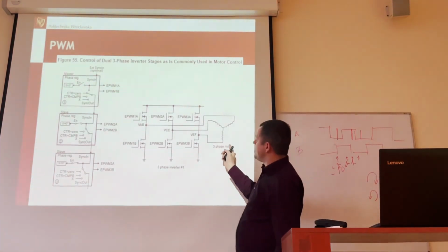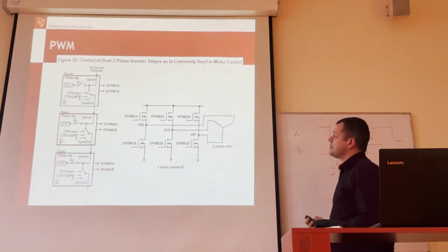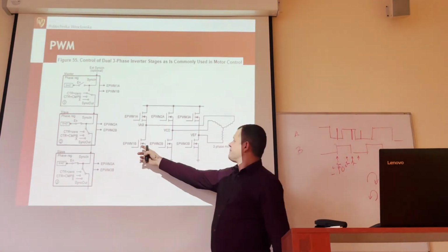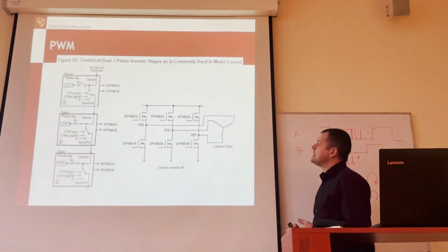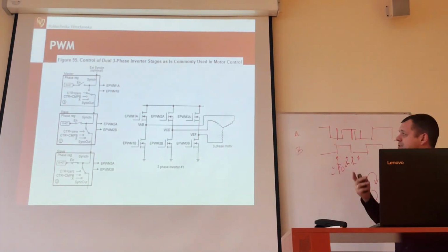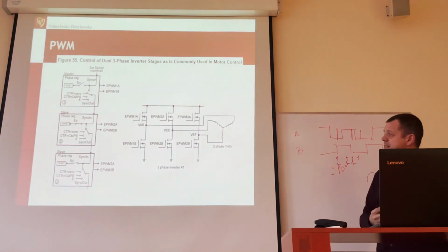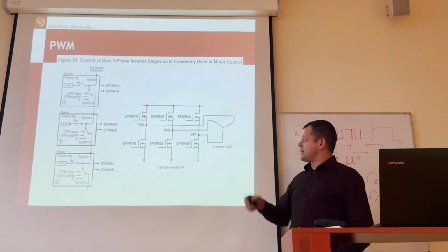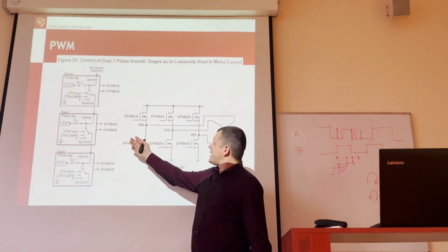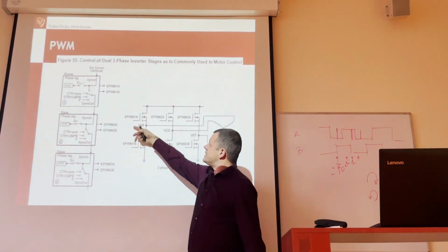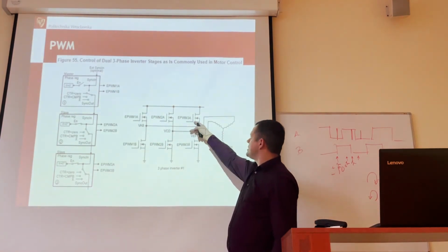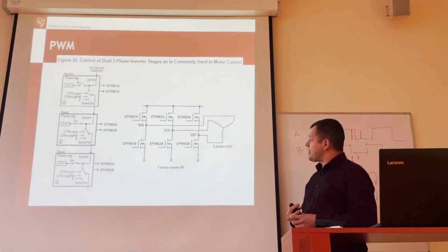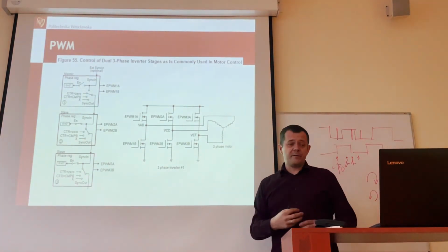So three-phase motors, the connections of three-phase motors, and why we need three outputs, why we need the three dedicated complementary outputs. So that's how we connect the PMSM or BLDC or in general three-phase motors to a microcontroller. Then we have to drive, of course, a PWM signal here, PWM signal here, PWM signal here. But this gives us the powerful so-called direct motor drive, very popular today.